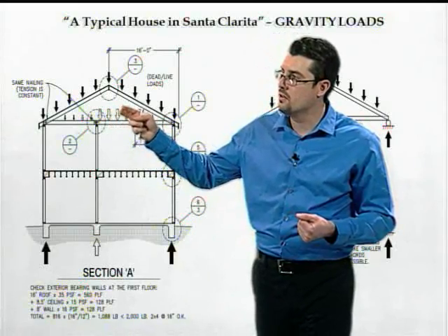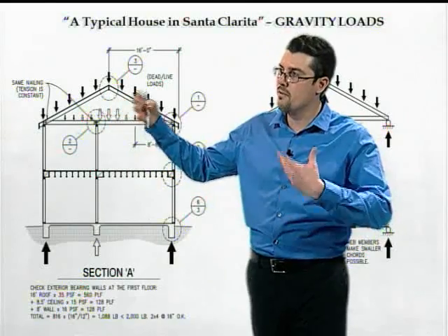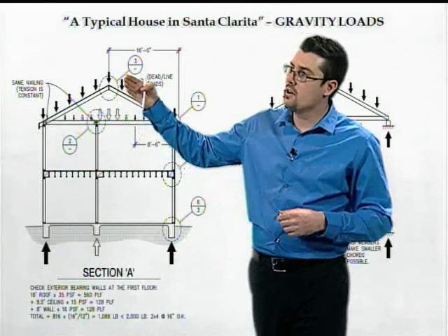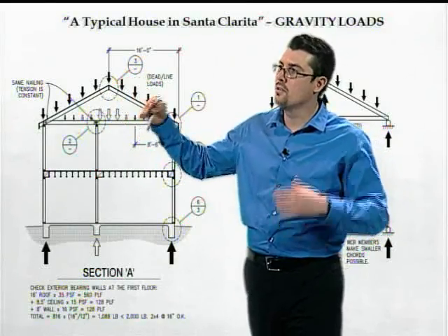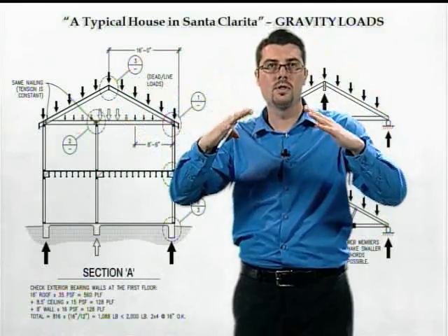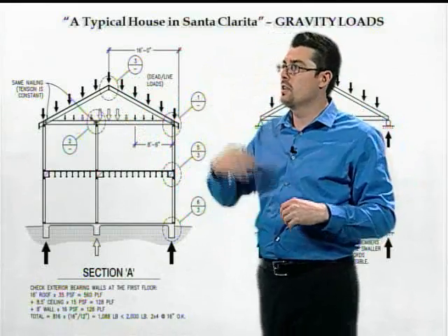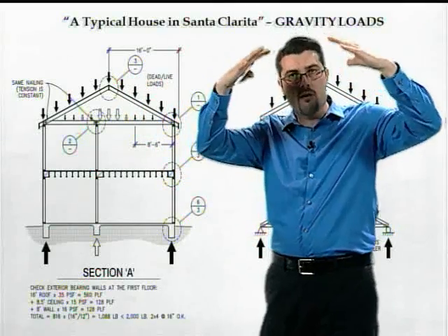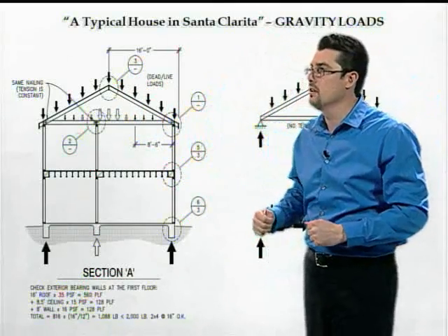Okay, so that's why you see these arrows. These arrows indicate the load, and the larger arrows are heavier storage loads in the attic. These arrows, the black arrows up here, are the roof dead and live loads. The tile, when they re-roof, they'll pile tile on. We account for that, and so that's the roof dead and live load.